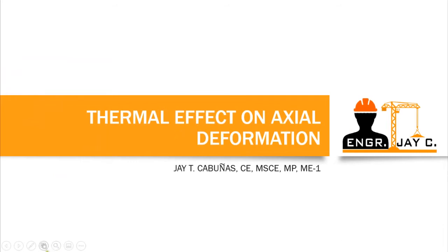Hello everyone, welcome back to another lesson in strength of materials. In this video we will learn the thermal effect on axial deformation. We will be learning the deformation of a bar that is loaded due to high temperature or due to a change in temperature.